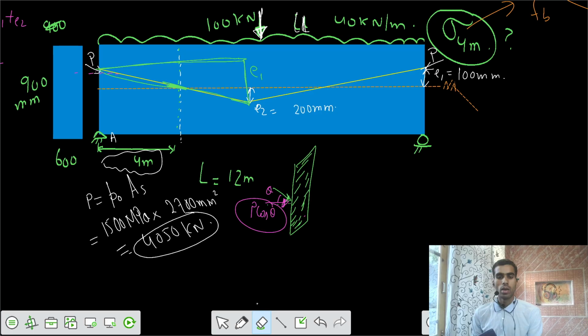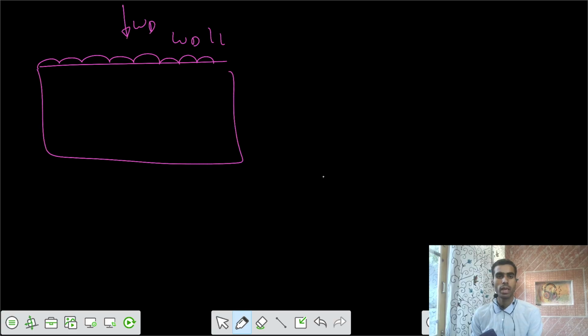From the question, we have a bent cable. If the question did not mention which cable to use, then we would have two different loads, one being the dead load and live load, and one the point load, and we would choose between a parabolic or a triangular cable.